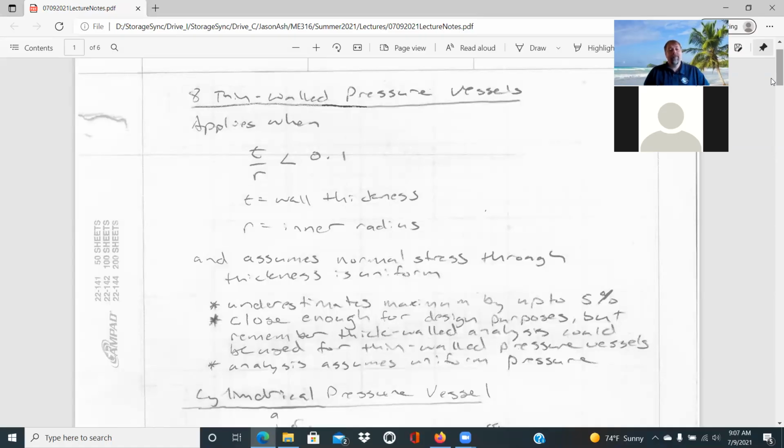And so that time period when there is a vacuum in that tank, that's acting as an external pressure vessel with atmospheric pressure pressing down on it when that air is evacuated inside. A submarine would be another example of an external pressure vessel, submerged in a fluid deep underwater, with a lot of pressure acting on the outside, pressing it inward.